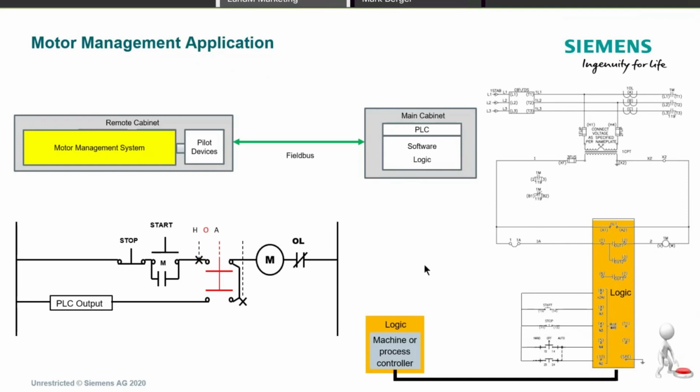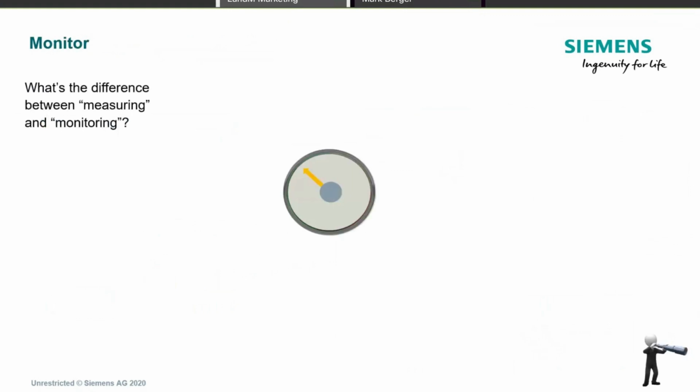Now that you're not wiring all those hard wires into place, the communication back to the PLC is via a field bus, which could be Profinet, Ethernet IP, Modbus RTU, or Profibus. Today we're going to center on Profinet. Again, here's the field bus outputs. And again, to emphasize, those two contactors go away with Simocode being introduced.